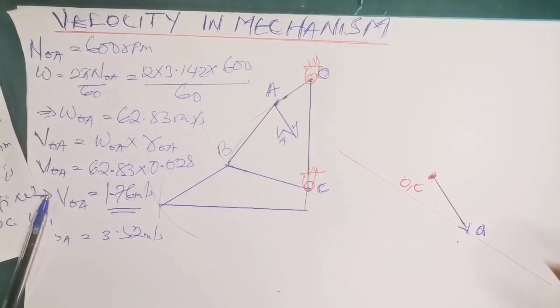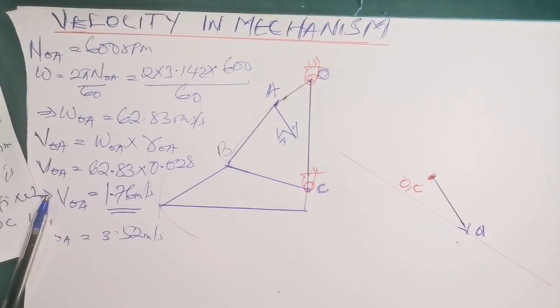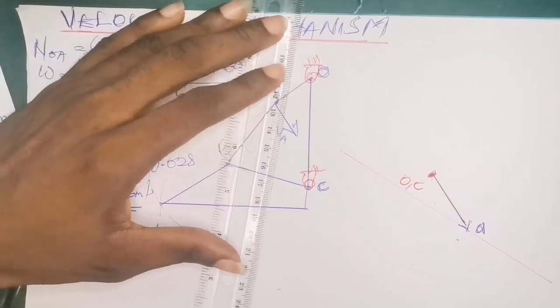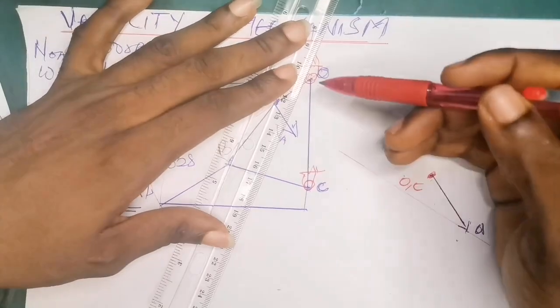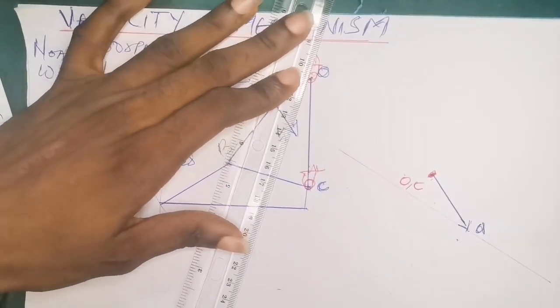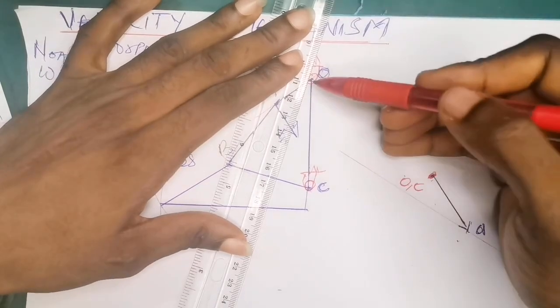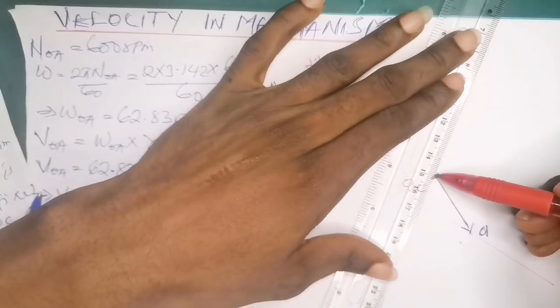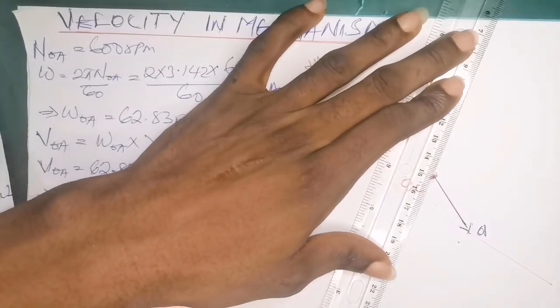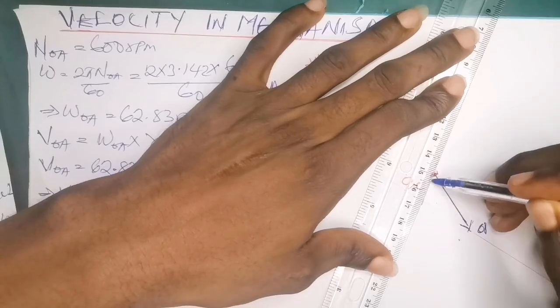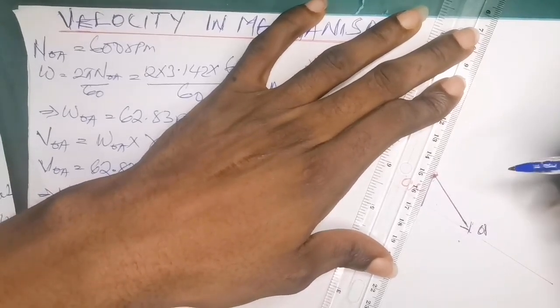So I've done from A to B. If this is A, either up or down is going to be B, but we're going to find out. Now from point B to point C, I have 90 degrees in this direction, which is going to connect to the fixed point O. If I trace this from here to this point, this is 90 degrees, so I can now join this with a thick line because now I am going to have a real dimension for B.